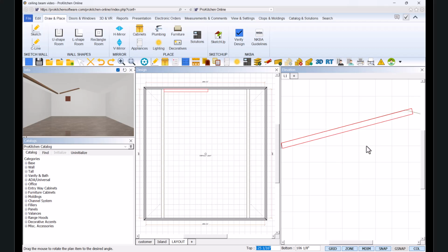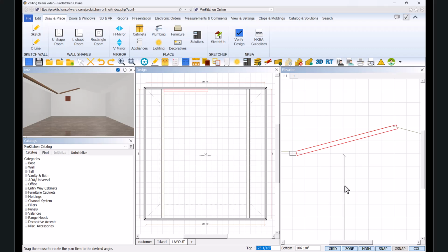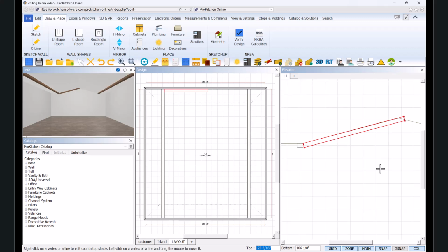Now to alter the ends so that they appear as the 45-degree miter cuts. For this, we will need to utilize the User Shape Edit tools. Right-click the user shape, slide into the toolbox, and select Edit. This will turn the outline of the user shape red and populate open points at each corner. For this process, we will focus on the corner points.